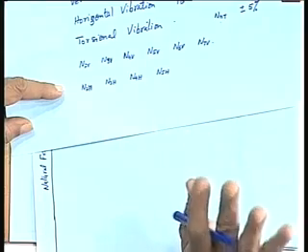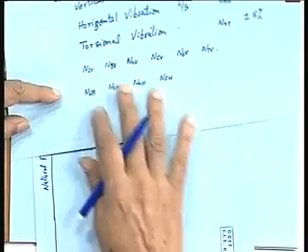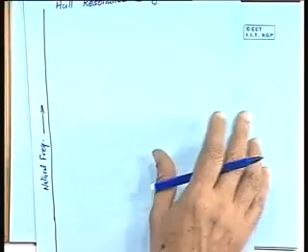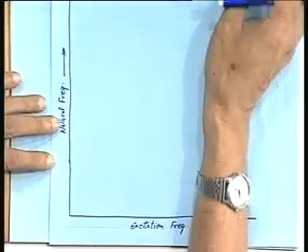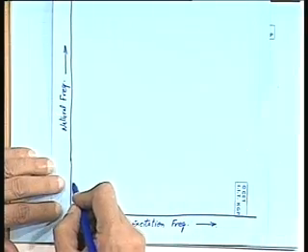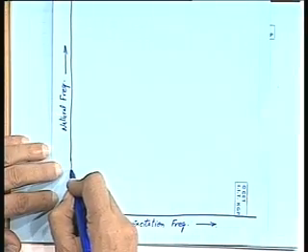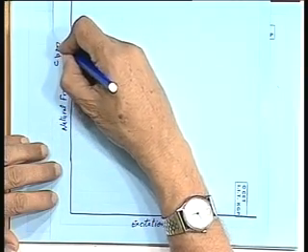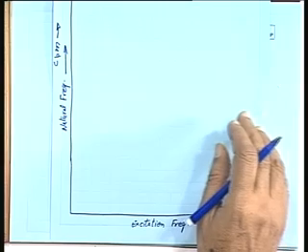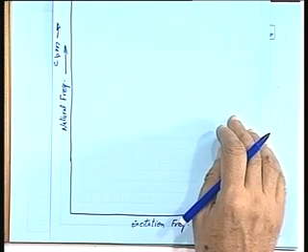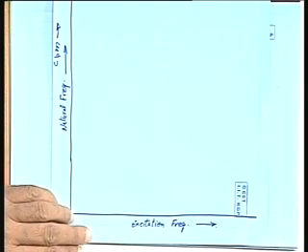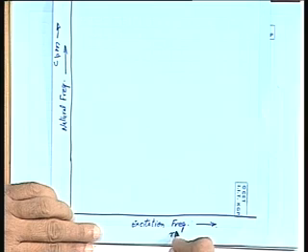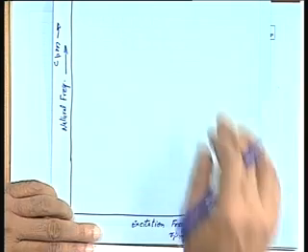Okay. For the time being, I am not taking the torsional frequency in this particular case, assuming that this is not a container ship, because a lot will only complicate the thing. So, I find that the fundamental frequency N2V is coming somewhere here. Now, these we will take in cycles per minute, because all this formula directly gives me cycles per minute, and the exciting frequencies also I take in RPM. RPM is revolutions per minute, so that is also basically cycles per minute.